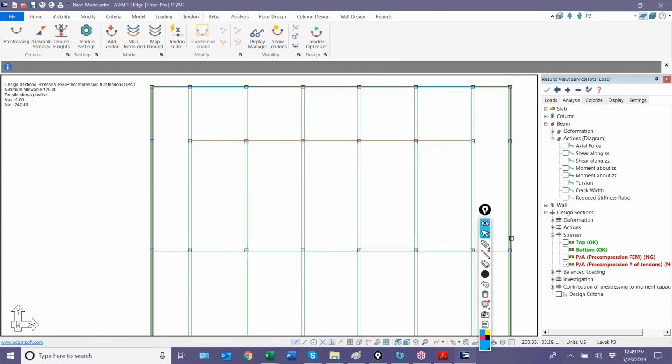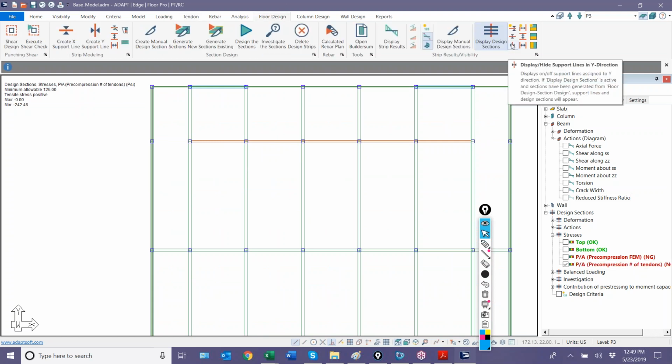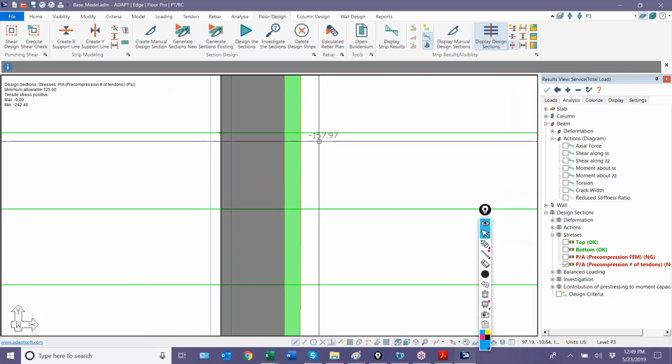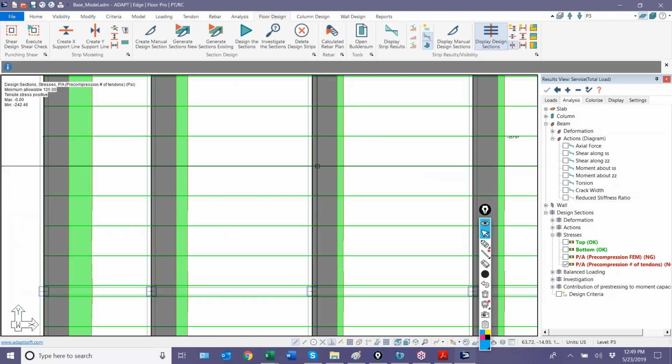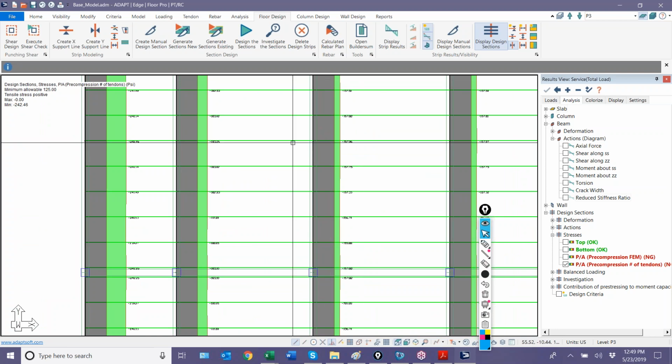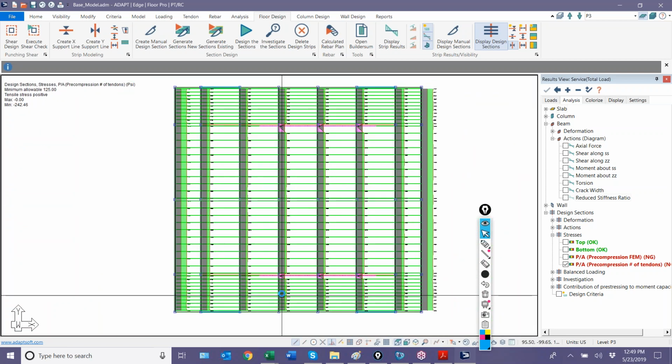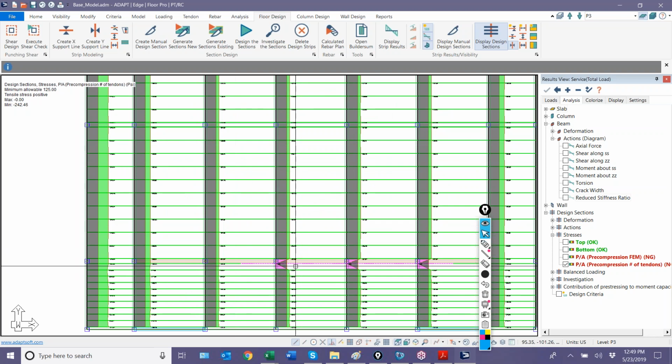And we'll go back into some results. So we know how to take care of the precompression issue. If I look back at the beam precompression, everything is right at about 150 or so where we targeted it. So everything here is really okay other than this strange anomaly relative to the other sections where we know exactly what's going on there.